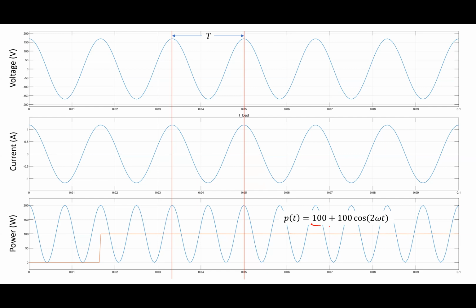Why did I do this? Well, because if I have a single phase system like I have here, what I have happening is when I look at the power, it's always, quote unquote, pulsating. It's got an average, but it pulsates up and down. That's what I call this behavior here, where it's going up and down like this, where it's got this variation. I call that a pulsation in power. We'll talk about this when we start getting into 3-phase at the end of next week.